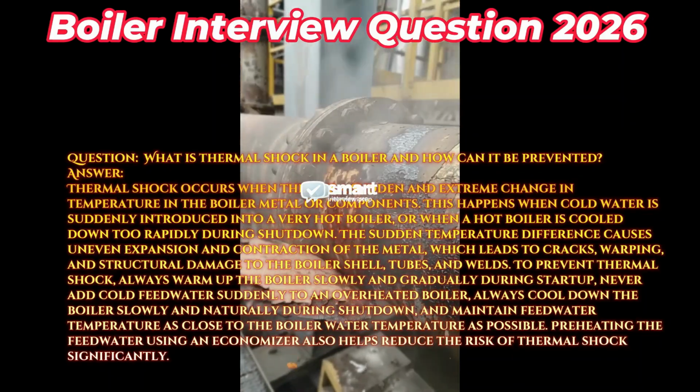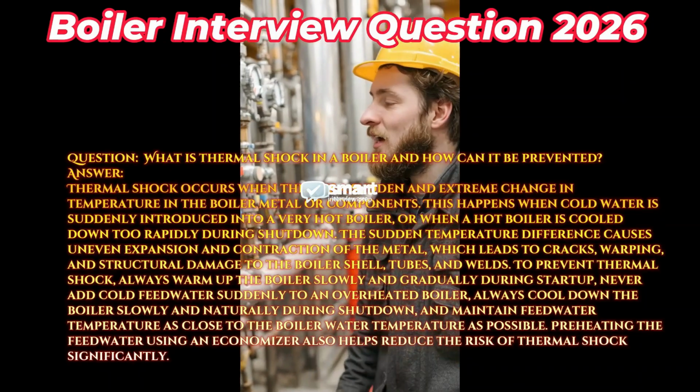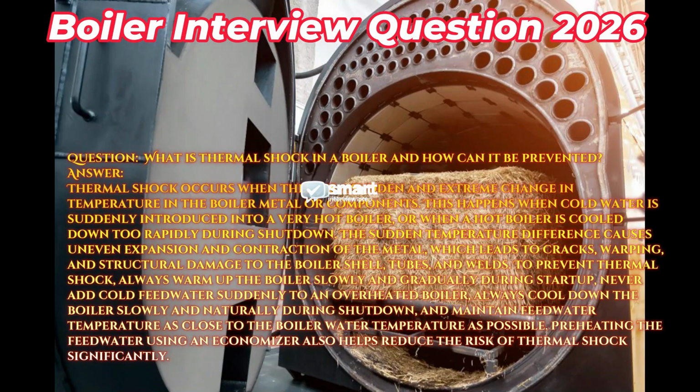The sudden temperature difference causes uneven expansion and contraction of the metal, which leads to cracks, warping, and structural damage to the boiler shell, tubes, and welds. To prevent thermal shock, always warm up the boiler slowly and gradually during startup. Never add cold feed water suddenly to an overheated boiler.